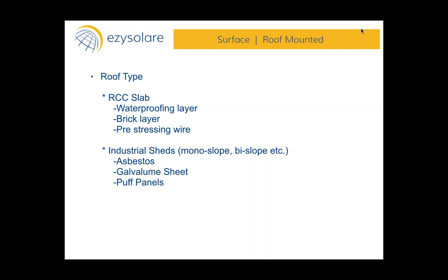However, ballasted structures are really gaining pace lately, and we see a shift. Ballasted essentially means the concrete blocks are already casted and then lifted to the roof, whereas in situ means you are casting the concrete blocks on the roof itself. Exactly. Whether in situ or precast, the idea of the concrete block is that whatever wind forces your structure will be facing, you have to hold down the structure.